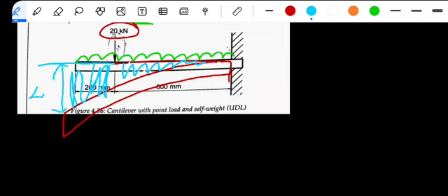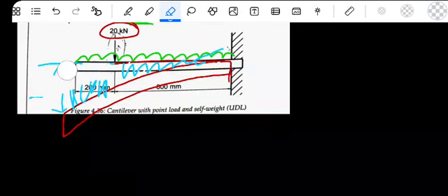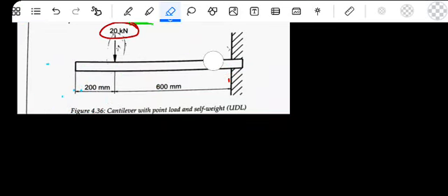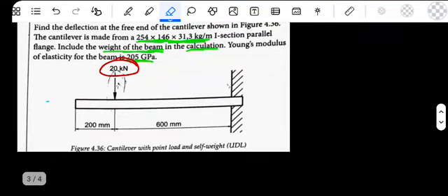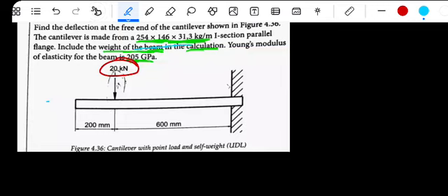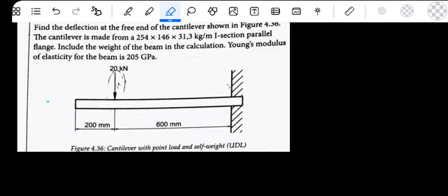So we know we'll have the two deflections. There's no need to go in deep, I've explained already, and I don't want to make this video very long. So you go to your steel table, check this on your steel table, then you find your moment of inertia there. So we took it.